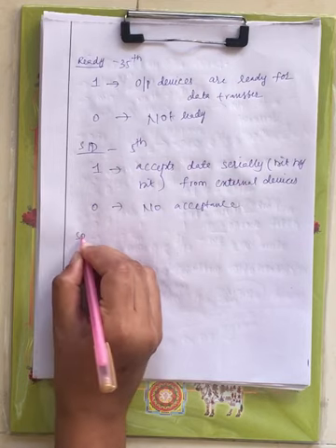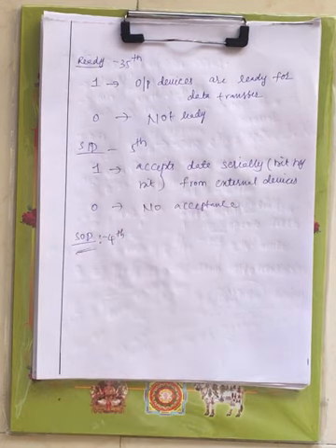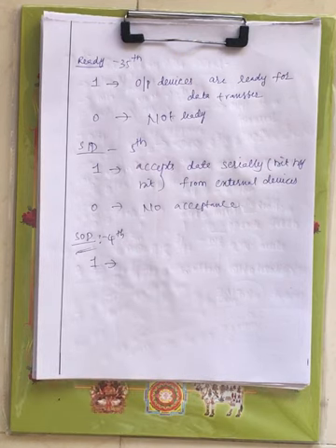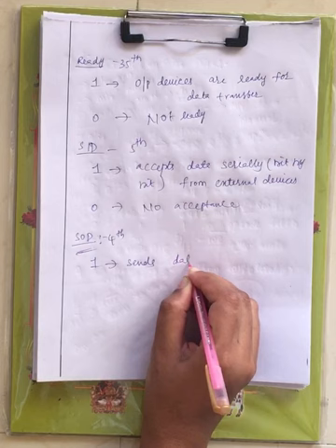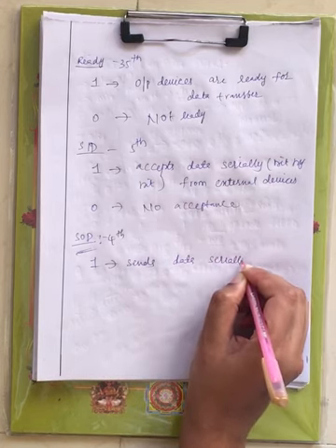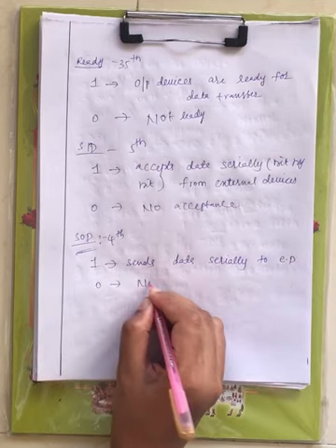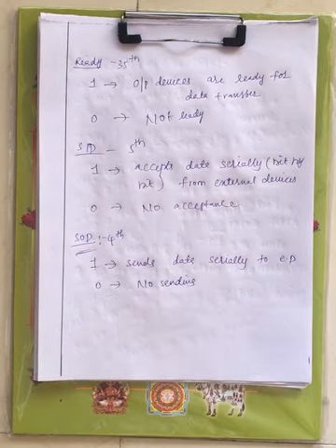Now coming to SOD, serial out data, which is provided at your 4th pin. When it is 1, it sends the data serially, bit by bit, to the external device. When it is 0, no sending. Now this is about serial out data.